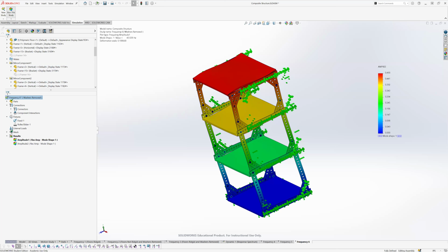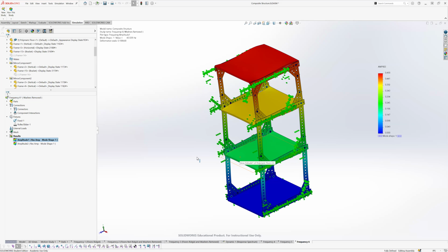So once you have your simulation set up, as you can see, it doesn't take that much time to modify and rerun the study. So if you need more frequencies, this feature is really nice, to be able to do it within a certain range, because then you don't need to worry. In our case with the earthquakes, a lot of the frequencies we're seeing were really, really low. Like some of them were 5 to 10 hertz. So by having that low of a frequency, there's really no need to go up to like 1,000 hertz or 200 hertz.